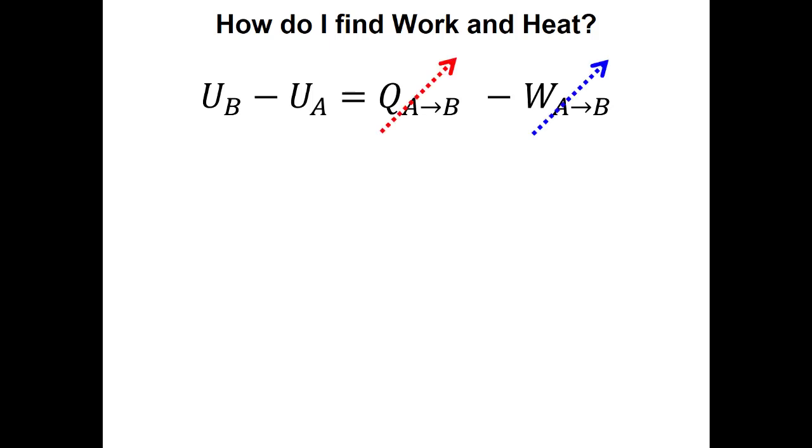But in this case, particularly when we're talking about the Otto cycle, we'll make the assumption that every process is a simple process. Now, that doesn't necessarily mean that it's easy to analyze. It means that every process, either work or heat, is the dominating component. So we're going to neglect either Q or W for all the processes inside this Otto cycle. So if we have a passive process, then that means there's no work. So that means we're either adding heat or we're rejecting heat.